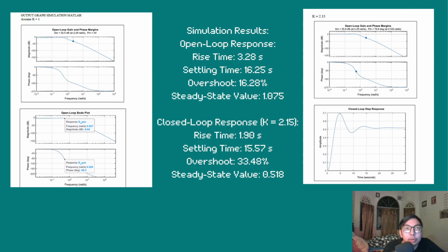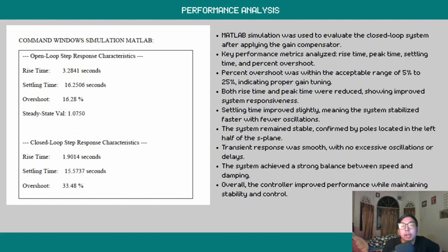And for additional, I find the step response for closed loop, which is this simulation. Continue. So performance analysis, the command window simulation in MATLAB, as you can see, I calculate the rise time, settling time, overshoot and steady state for the open loop and the closed loop.